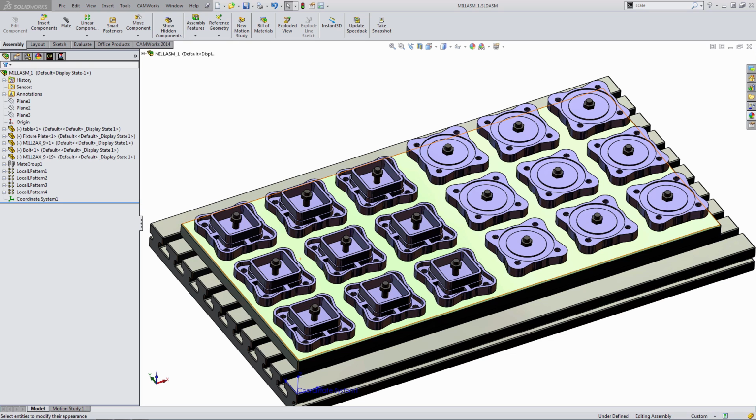There are going to be some steps here at the beginning that are very important, and I'll spell those out. One big thing to remember at the beginning is that assembly mode is only accessible in milling mode. So if you are doing turning or mill turn and you try to create an assembly, you're going to be wasting a few minutes of your day when you try to program it inside CAMWorks.